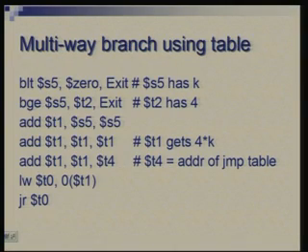by doing a multi-way branch by a single instruction. So, a new instruction which is JR, jump on register content, will be used here. So, we will do this with the help of a table. Okay. What we have is that in a table we have all the starting addresses of different cases, okay. And then we simply look at the value of k, use it to pick up the right address from the table and jump to that. So, let us see how it is done.